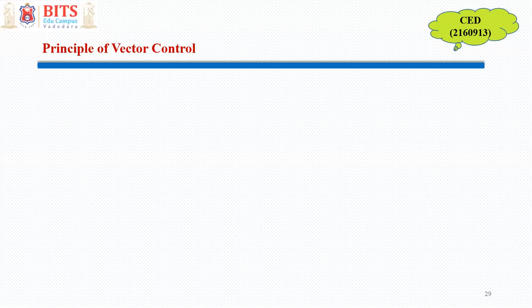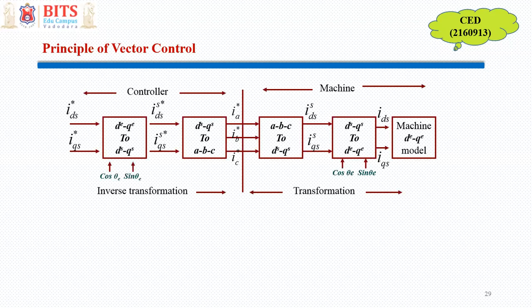Right. So for those who were not there in yesterday's lecture, this is the block diagram of a vector control approach. So in vector control, we assume as if it is possible to have two components of the controlling variable, D component and Q component. And we mathematically do all the necessary transformations such that D component is the component along which the flux is directed, aligned, and Q component is perpendicular to it, and it is affecting the torque, right?